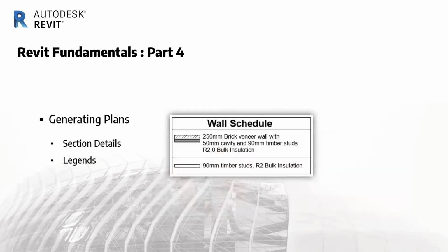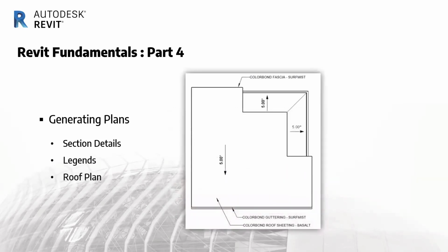We'll next create a wall legend from the legends command, and then we'll go on and create a roof plan and add some annotations like the spot slope, etc.